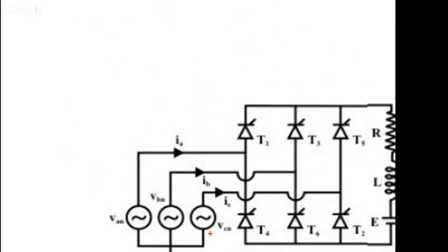If it's a three-phase supply, you have to remember that based on the number of phases you define this. Always the odd ones at the top: 1, 3, and 5. Now it is a three-phase supply, so 1 plus 3 gives you T4. Then 3 plus 3 gives T6. And 5 plus 3 is 8, but 8 is not there, so minus 6 again, you get T2. This is how you define which are the thyristors.